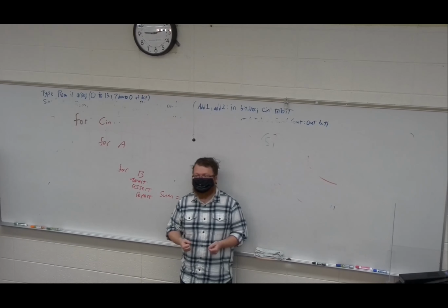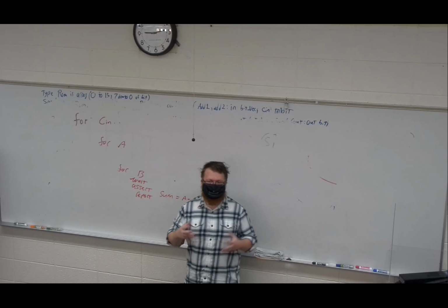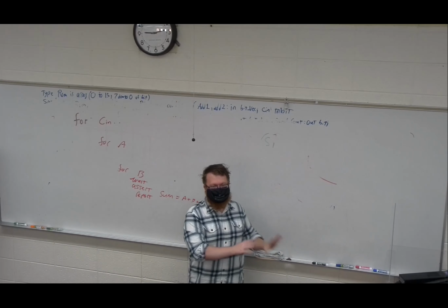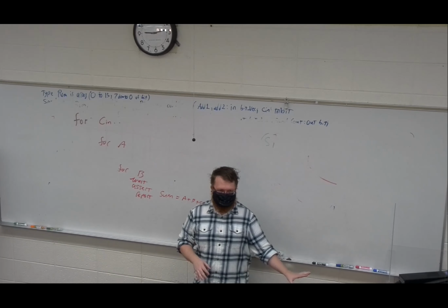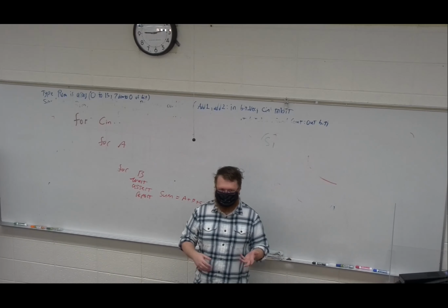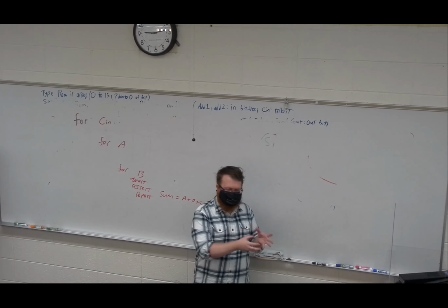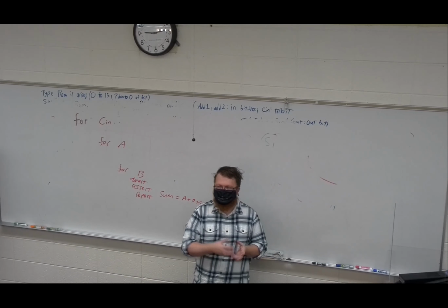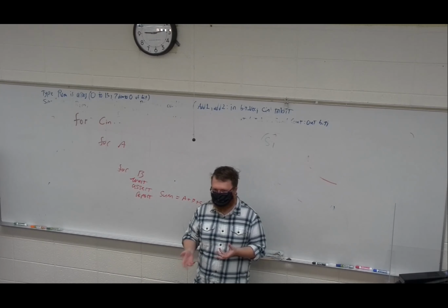So there is a tool that we can use called a Debug Core. A Debug Core is a tool that Vivado provides for us that is a soft core, a little processor, so it takes up a fair chunk of room on your FPGA. Not really an issue for us. We have tons of room on our FPGA compared to what our design is doing.